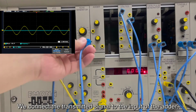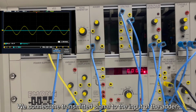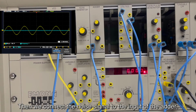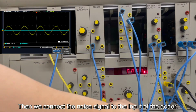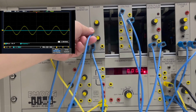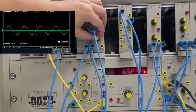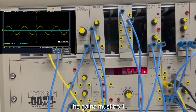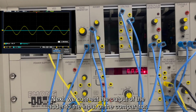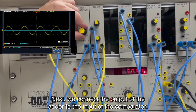We connect the transmitted signal to the input of the adder. Then we connect the noise signal to the input of the adder. The gains must be 1. Next, we connect the output of the adder to the input of the comparator.